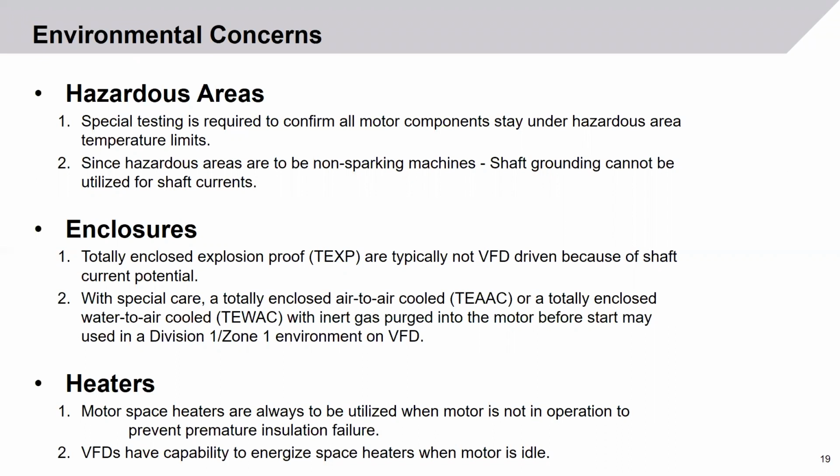Other enclosures that may have problems, now we'll talk about Division 1 or Zone 1, are the totally enclosed explosion-proof motors that are typically not VFD driven because of shaft current potential. However, with special care, a totally enclosed air-to-air cooled, otherwise known as TEAAC, or totally enclosed water-to-air cooled, otherwise known as TEWAC motors, with an inert gas purged into the motor before start, may be utilized in Division 1/Zone 1 environments and can be driven by a VFD.